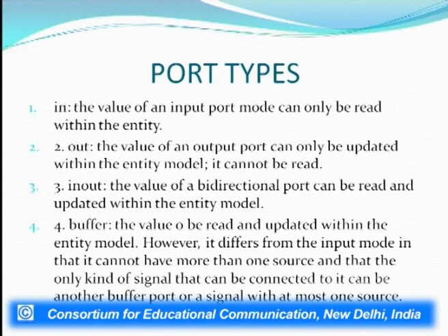So, any signals that are bidirectional, for example, those used in case of feedbacks, can be declared as input-output type. Another type is the buffer. The value can be read and updated within the entity model. However, it differs from the in mode because it has the capability of storing also, and it cannot have more than one source. It can be taken only from one source, and it can be connected only to a buffer type and at most to one source.